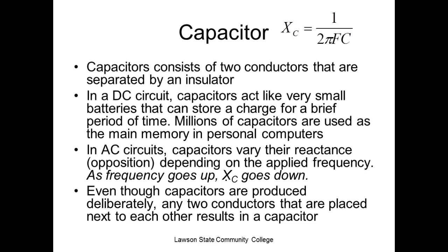So that's what you used to do when you were tuning your TV or your car: you were setting up what we call a tuned circuit. You left the inductor alone and tuned the capacitor, or you left the capacitor alone and tuned the inductor. Once you set up a resonant circuit at a certain frequency, it would let that frequency come through. We still see that on our radios in our car. You don't see it in your TV because they don't give you the frequency of these different channels. All you've got is a channel number, right? But on your car, you still see the frequency of what we call the carrier.